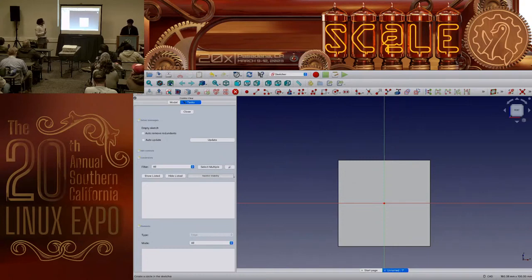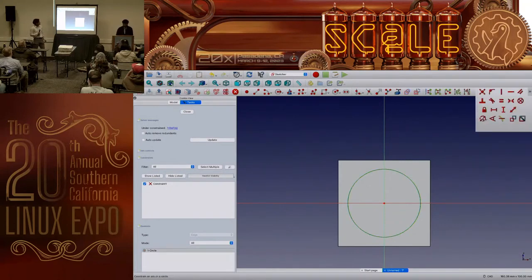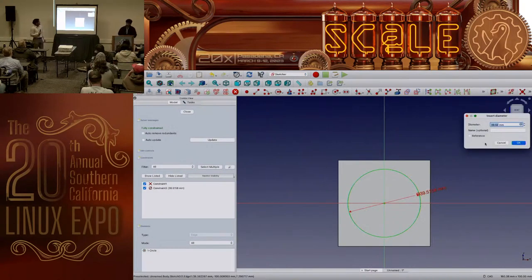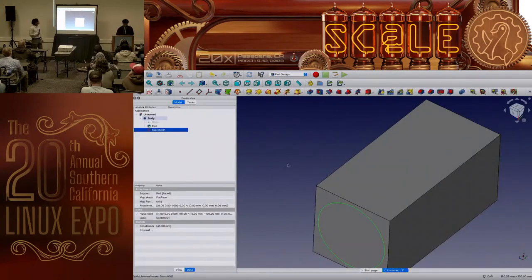Okay, so for our hole, we'll do a circle since I already covered a rectangle shape. So we'll create a circle. Obviously, we want it about the origin. So I'm going to click the origin. Okay, so I drew our circle, but what's it still missing? A width, perfect. The dimensions, correct. Okay, so we'll click our circle, and we're going to constrain it using constrain arc or circle. So we'll click that. Someone throw out a number. 45, perfect. Okay, so as you see, our circle turned green, meaning it is constrained. So we'll update that. Close it.